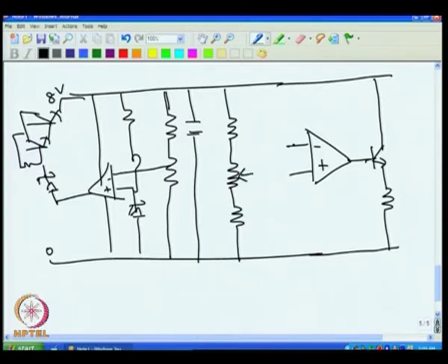This is the potentiometer. When the mechanical system moves, the center tap of the potentiometer actually moves. So, when the mechanical system is at one end, the wiper will be at this end, making contact here. When the mechanical system is at the other end, then the wiper moves and makes contact at this point. If it is halfway, then the center point will be at the halfway point of this potentiometer. Normally, for example, they use this 5K part actually. So, essentially what is happening is when the mechanical system moves, the voltage from the center tap to ground actually varies.